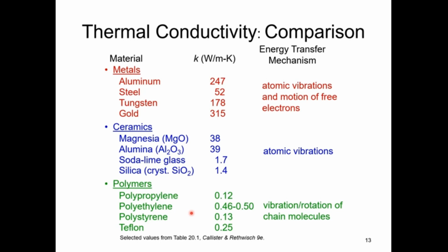Metals are very good at conducting heat for two reasons. First, heat transport is much more efficient because electrons are not as easily scattered. Because they are bound together via metallic bonds, the electrons are not easily scattered, and they have very high velocities. The second reason is that metals have a relatively large number of free electrons that participate in thermal conduction.